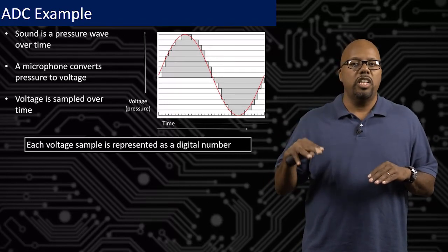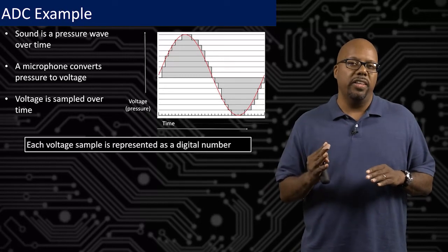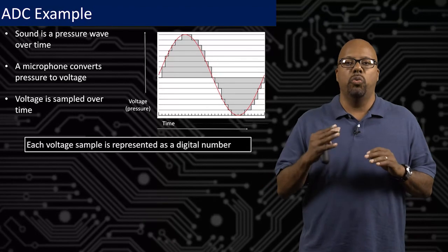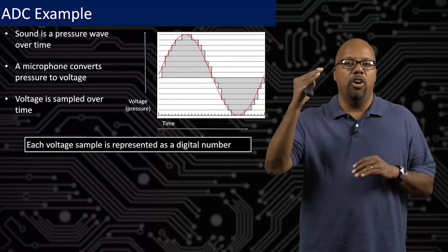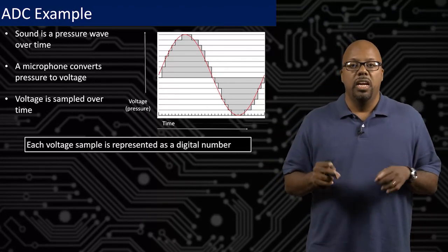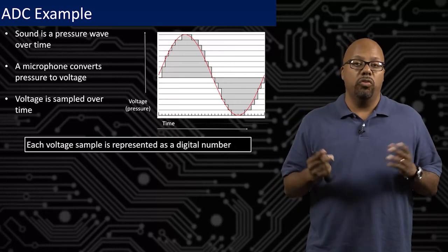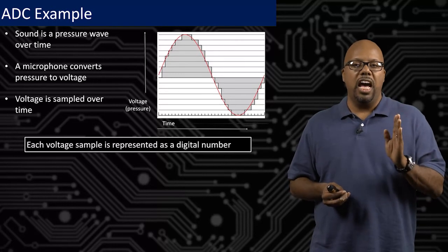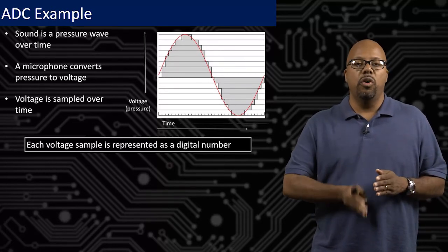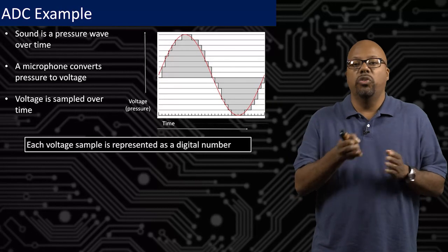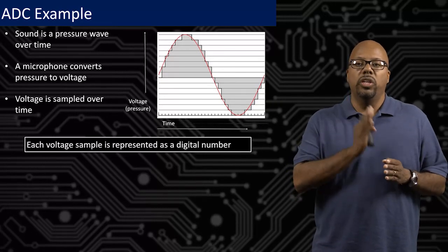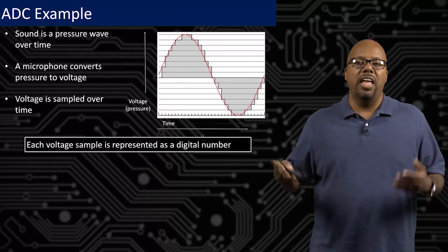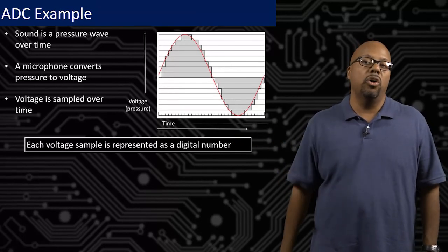And if you look at that stair-stepping waveform that's overlapped on top of the analog waveform, it only ever hits one of those lines. It's never in between, right? It's at a line or up or down, right? That's digital. So you can take this analog waveform, this red one, and approximate it with this stair-stepping digital waveform. And so at every unit of time, the digital waveform is always at a fixed voltage value in this case, right? And so you can just have a series of voltage values over different points in time and store it, and that is an approximate representation of this analog waveform.